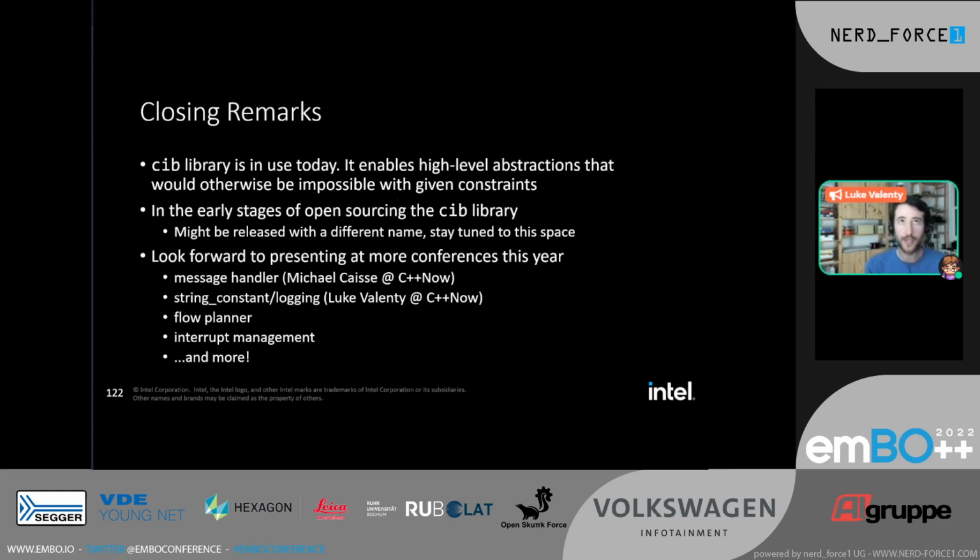And so for the interrupt manager, I explicitly don't want to erase the type. So I want to use the one from the nexus. And I do that because I want to call some template parameters. When I call the interrupts manager, I pass in the interrupt number as a compile time value so that we can completely inline the ISR in the actual hardware ISR. There's no indirection with function pointers there.